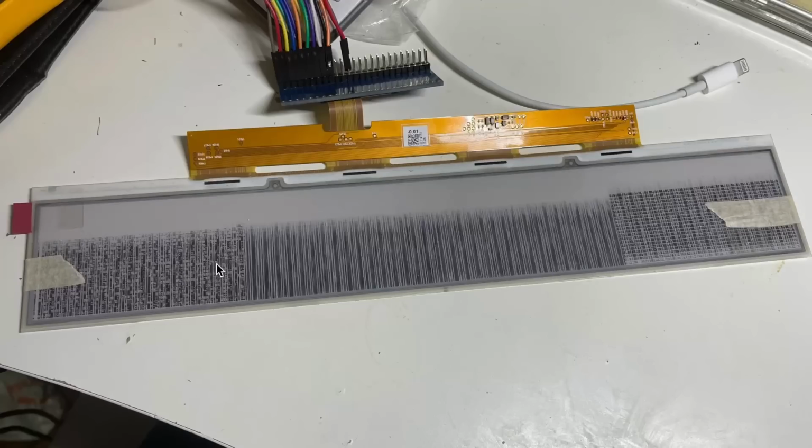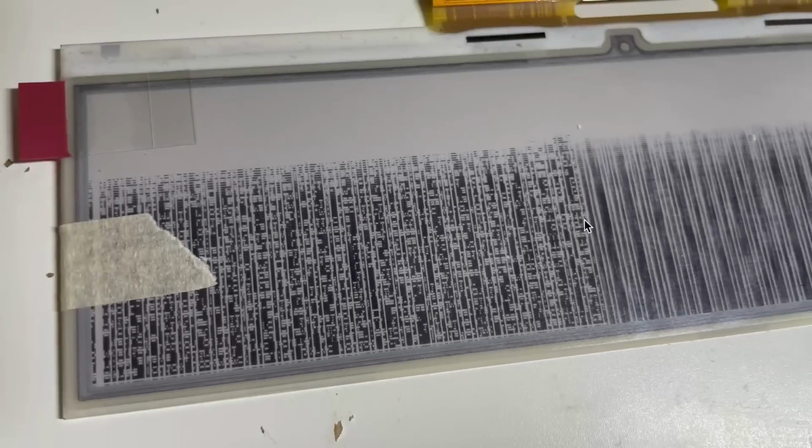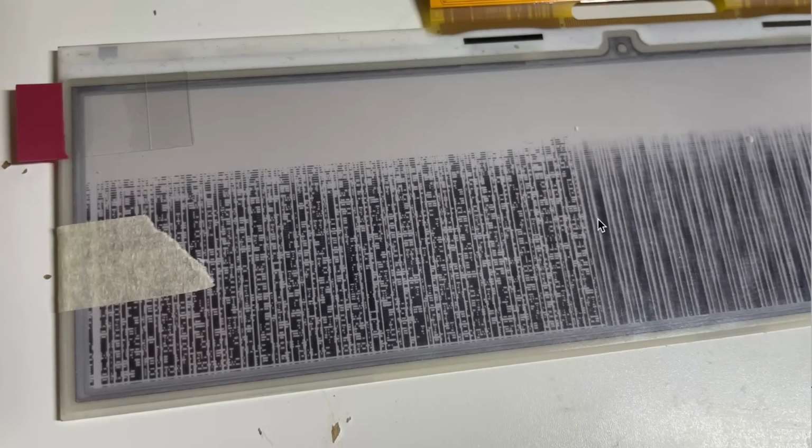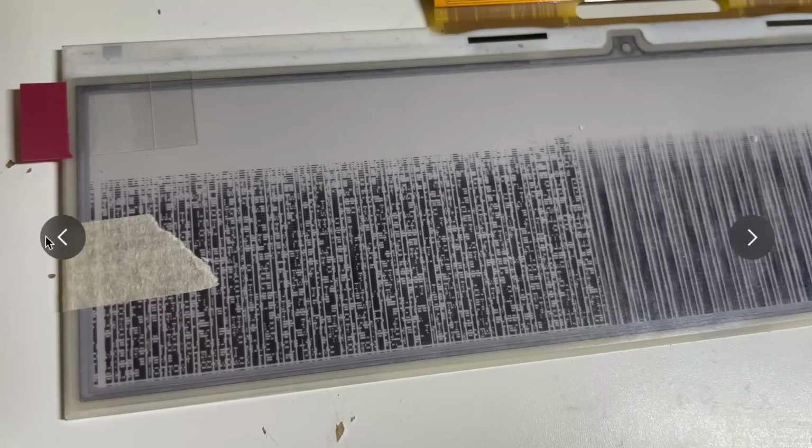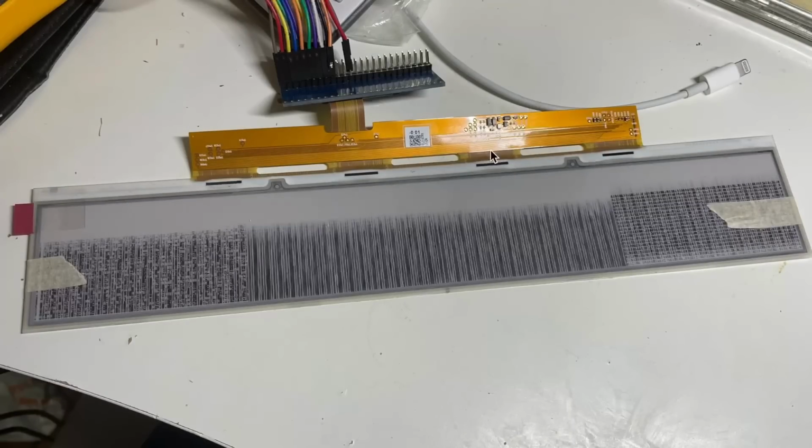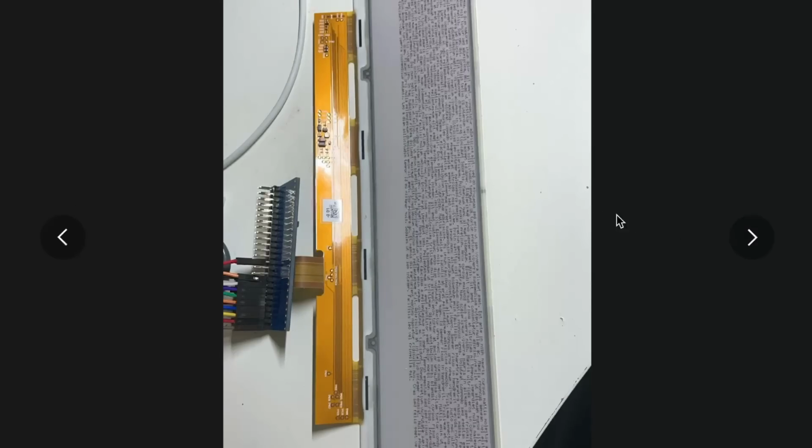There is some reasonably garbled stuff on the side. If you look closely, it does kind of look like text, but definitely not correct. It's kind of missing every other line, and the middle part is completely garbled. This pretty much tells me that the 4 chips are not working in sync. And guess what? I never configured the synchronization register. That's probably the reason. So after configuring it, I'm getting this.